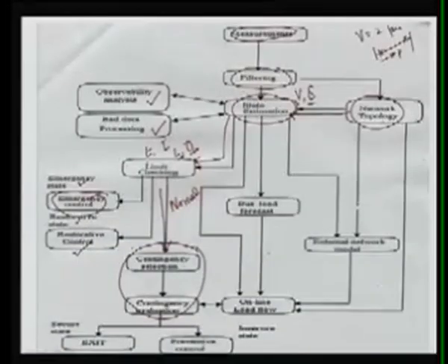So it is very important that this block, called the contingency or security analysis, is only performed if your present operating system is in the normal state. Otherwise, if it is not in the normal state, then we have to take corrective action or preventive corrective action so that we can bring your power system to the normal state.